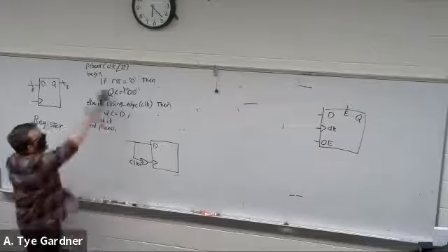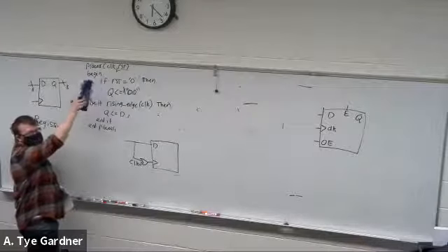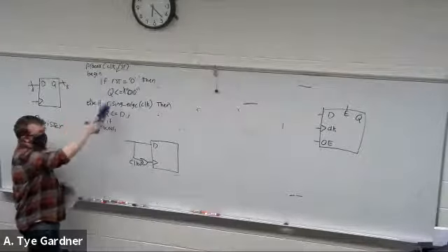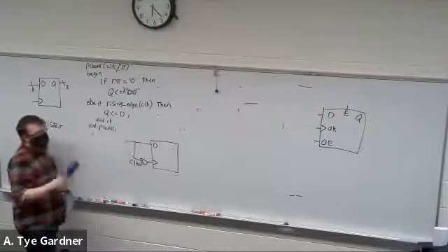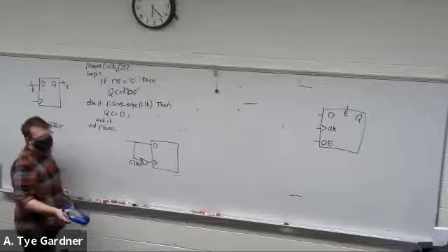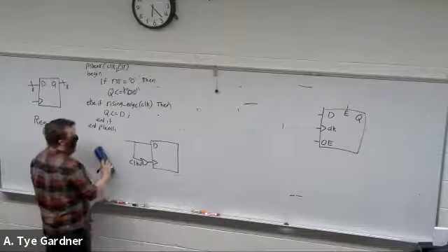So be aware when we're doing sequential circuits in this class, we almost always want to do synchronous circuits with the exception of the reset being asynchronous. Okay.